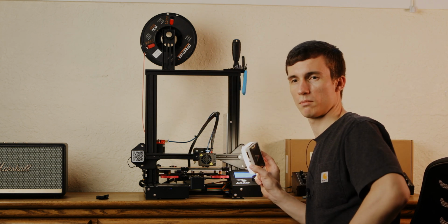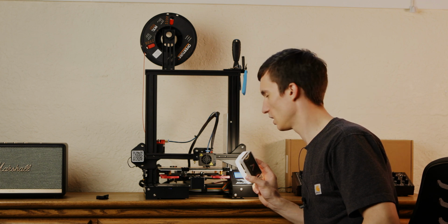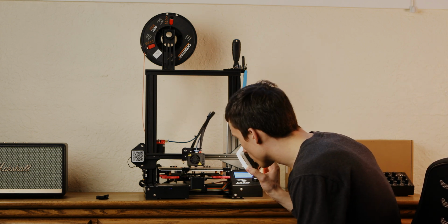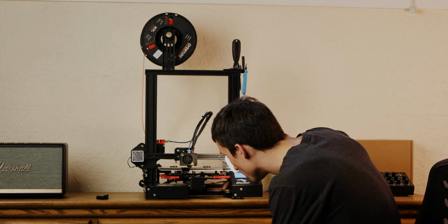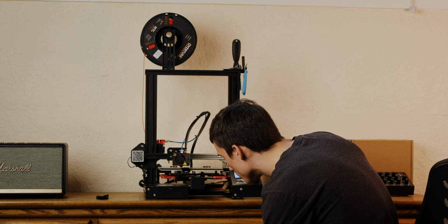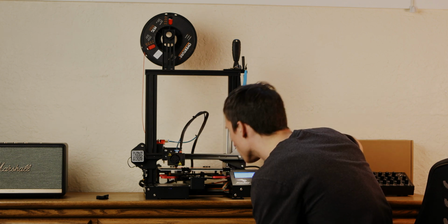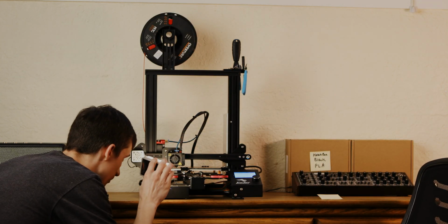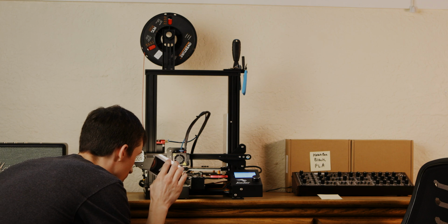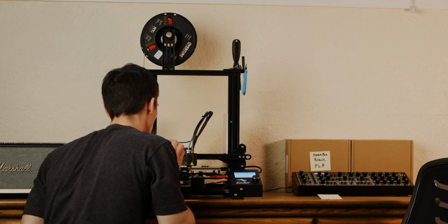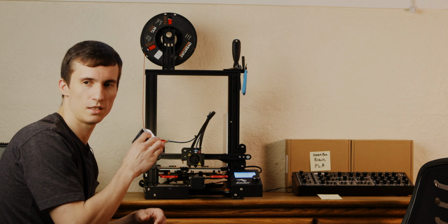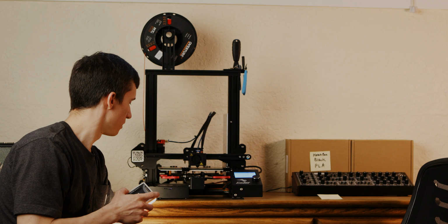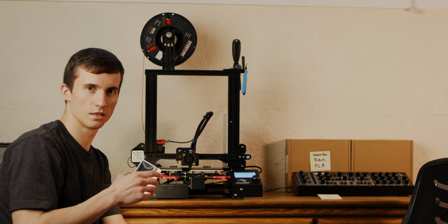So this is why I print a brim. It's a good time to just fine tune all the settings on the fly as it's printing. I'm going to go ahead and wash that corner again. Looks okay. What I would like to see is the lines sort of squishing just a tiniest fraction into the other line. So like laterally, the adhesion.